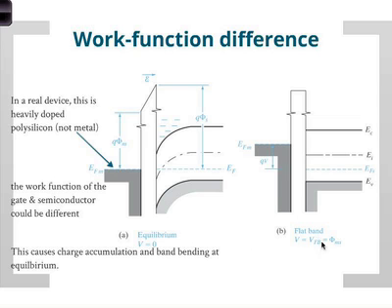In this case, we can see the flat band condition is just a difference in the work functions between the metal and the semiconductor. Essentially, you pull that up, you reduce the band bending, and then you don't have accumulation anymore. Now you have reached our old equilibrium. So you can think of the flat band as the starting point of operation of a transistor.